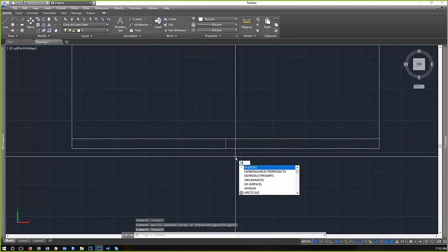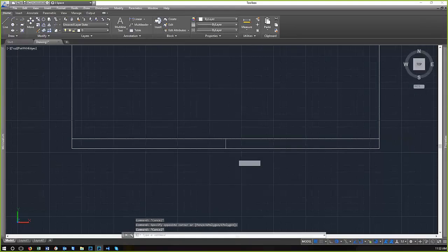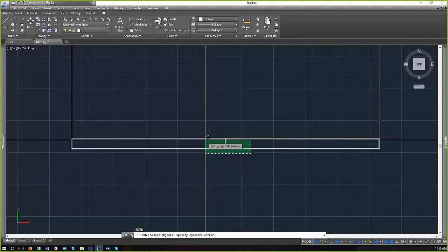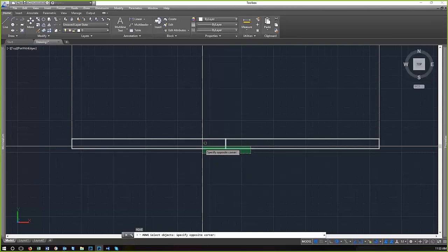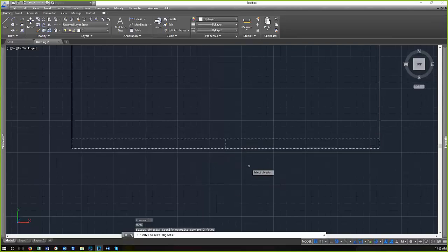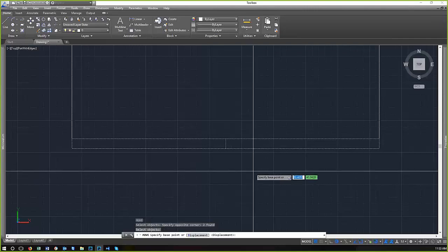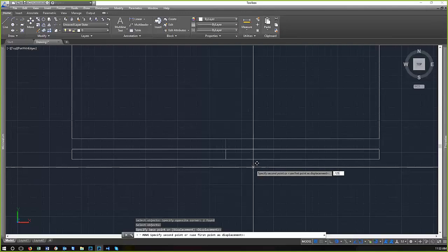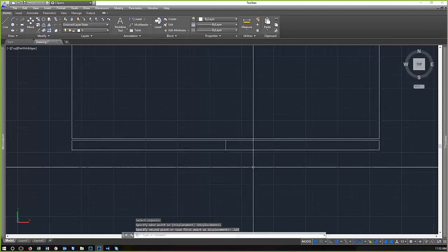So let's move, hit an M command, and then enter, and select what objects you want to move. I'm dragging up and to the right so that I can grab anything that the lines touch. So I'm grabbing those 2 doors. I'm going to hit enter and give it a base point and move down something like 0.125. Done.